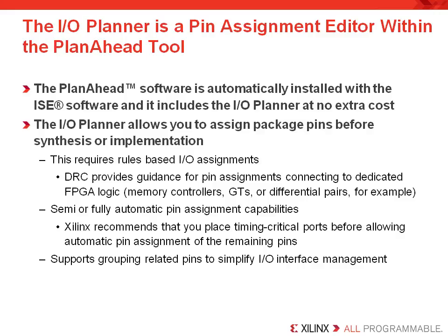So as I mentioned, PlanAhead and the I/O Planner are included with the ISE software. The I/O Planner can be launched from the Project Navigator. The I/O Planner supports making your pin assignments before synthesis or before implementation. This is important because most customers are locking their pins down before the HDL code has even been written.